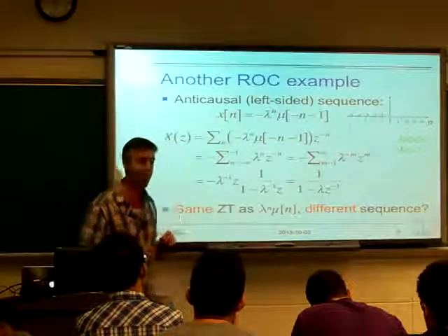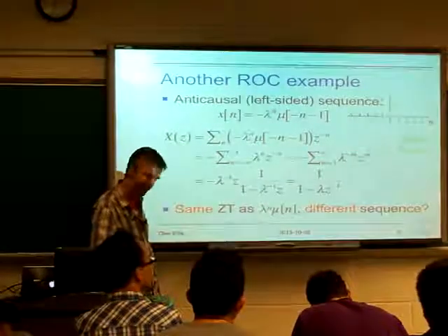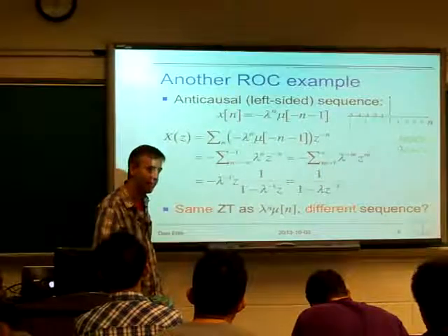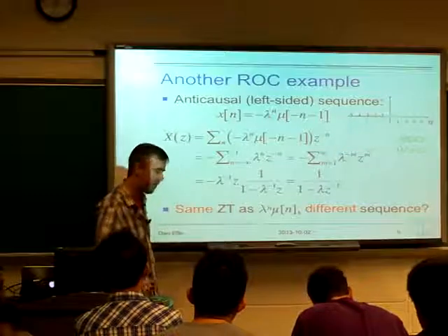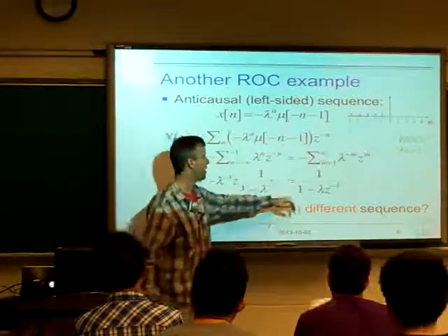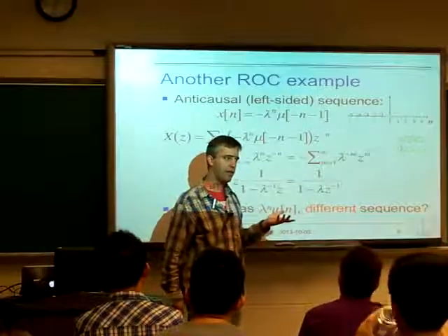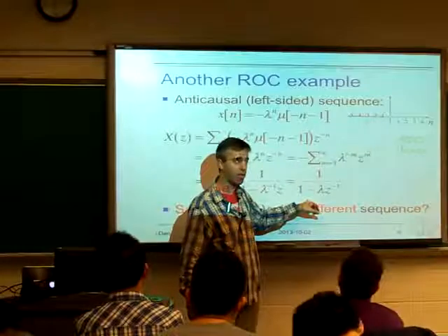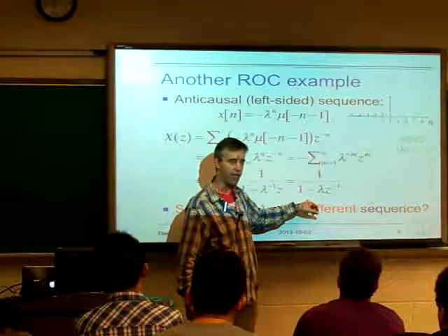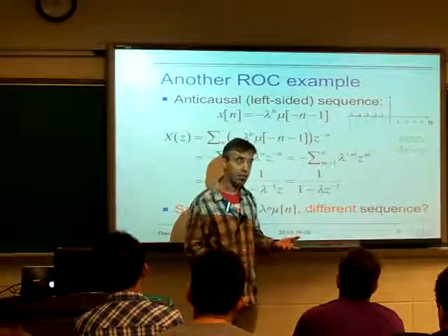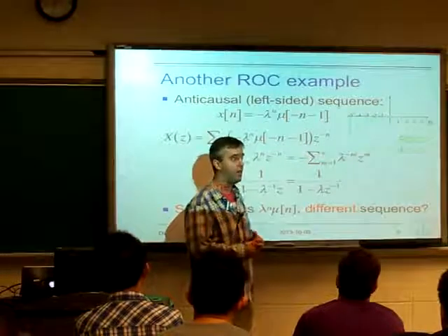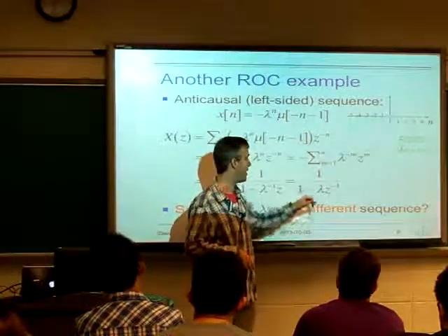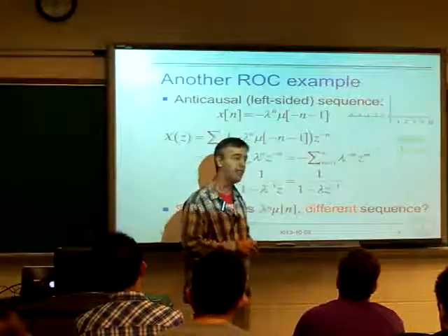If you're given a z transform of some certain function, how will I know that it is from, for example, a causal sequence? That's great. So if someone gives you a z transform like this and says, what sequence does this correspond to? It's like, wait, you told me the closed form expression for this z transform, but you didn't tell me which values of z it was valid for. It's not a well-formed question, right? I have a z transform, and over some values of z, I can tell you what its values are, but I'm not telling you which values.